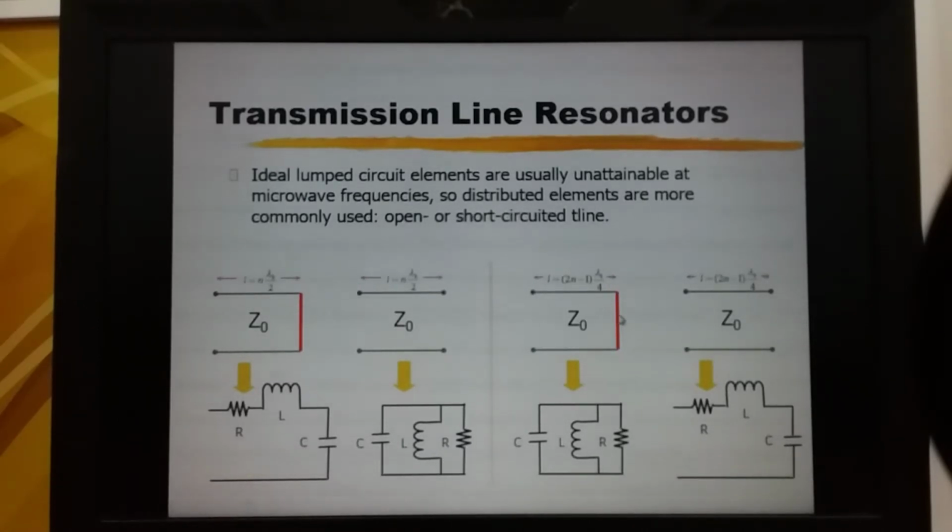So 0 ohm is transformed to infinity ohm. Similarly, we only get infinity ohm at exactly the resonant frequency. If the frequency is slightly higher or slightly lower than the resonant frequency, we will have the impedance lower than infinity. That is the behavior of a parallel resonant circuit, which can be represented by a parallel LC network.